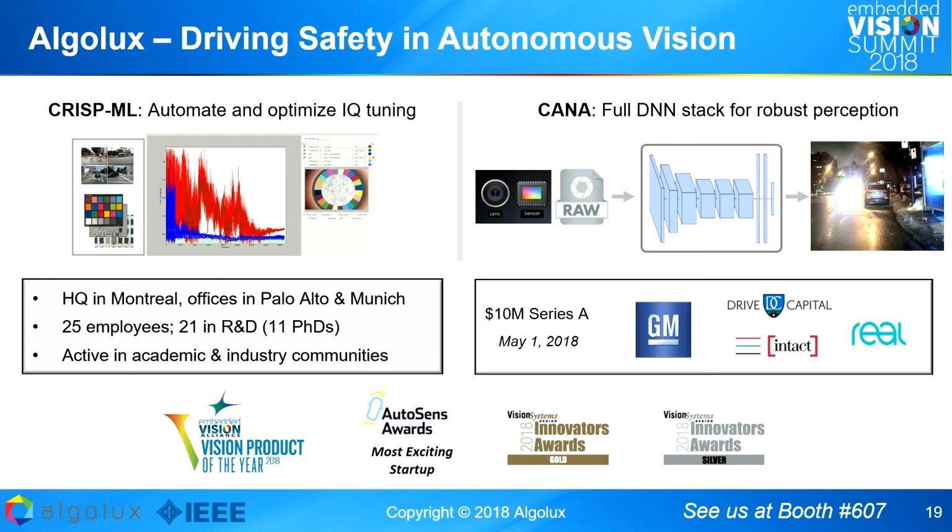But can you apply your vision KPIs straight to the output of the sensor? Yeah, exactly. You can apply them straight to the sensor, but you still need a trunk of an ISP. You can basically say, okay, I only do, I don't know, bilinear demosaicing or something very simple, so that I just get an image on which I can measure contrast detection probabilities and other things. The color metrics propagate very easily even through raw data. But for spatial information, you have to modify these metrics.